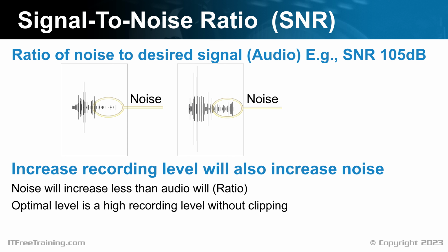To get the correct levels, most recording equipment will have some way to measure the audio level. Often this would be the use of a volume unit or VU meter. To get the optimal level, generally you want the audio to be between 50% and 75% on the VU meter. This is an average, so for example, if you are recording audio of someone speaking, you want the level to be within this range. Clipping will occur when the audio gets too high, so if you find your audio is in the high range, there is a chance it will be getting clipped.